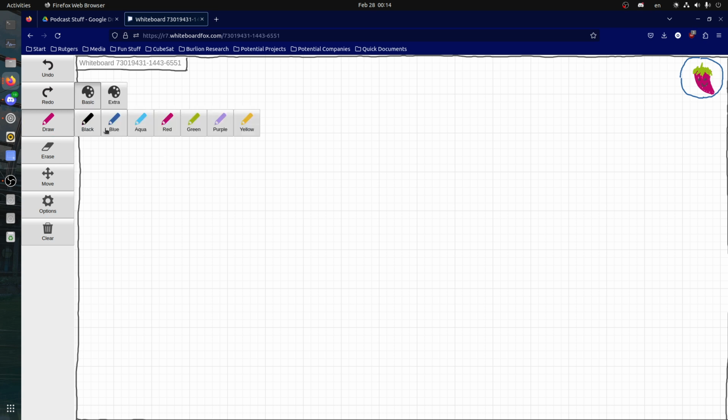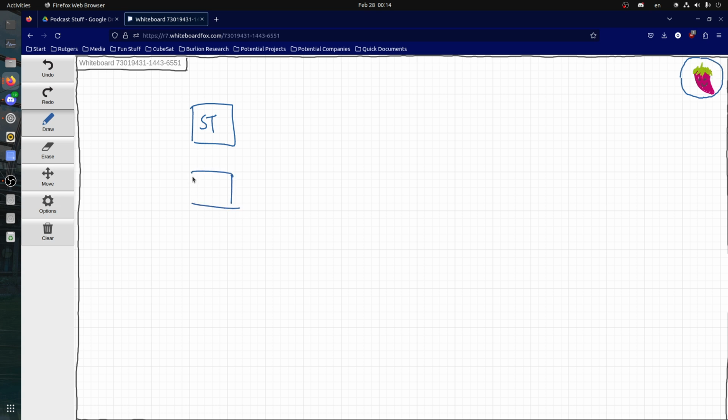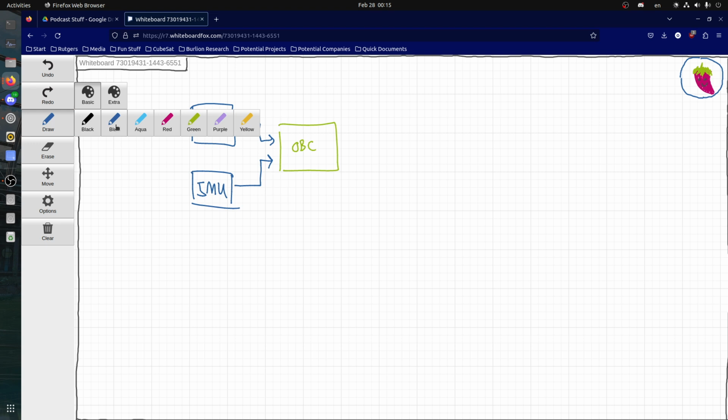So every component that I've talked about will have errors, right? Your star tracker, it runs very slowly. Your IMUs, they're prone to drifting. I'm gonna call this the OBC. Your OBC will have a time delay attached to it, right? It's gonna take time to process the data and give you the value out.